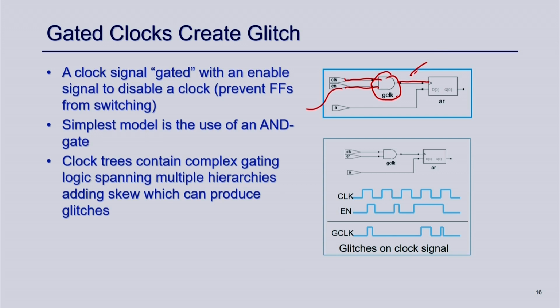So, how can we prevent that? The example is written here. This is my clock and this is my enable. You can see here there are some glitches, and this is the actual data. Since the clock is 1 here and this part of the enable is 1, there will be a glitch created here. For example, here this is 0 and there is a glitch, but it will not be propagated because it is ANDed.